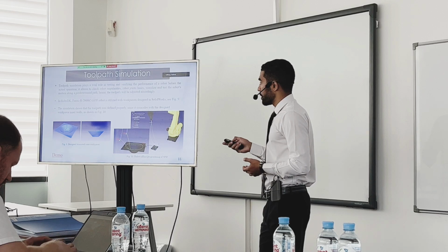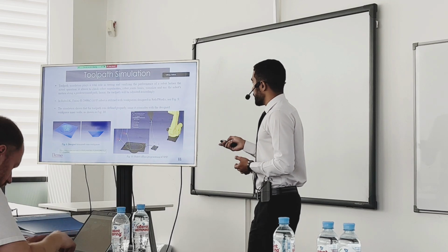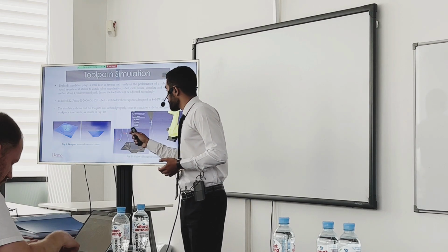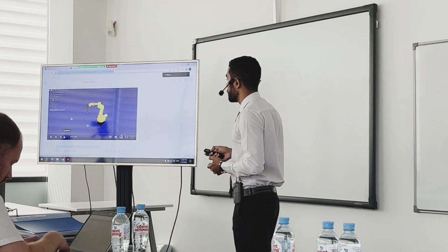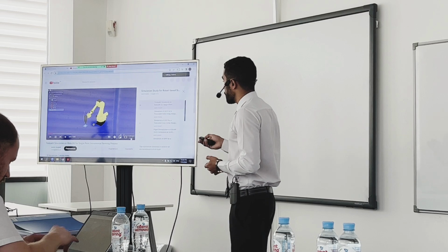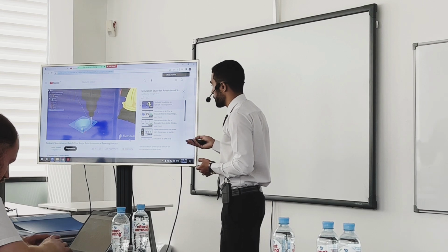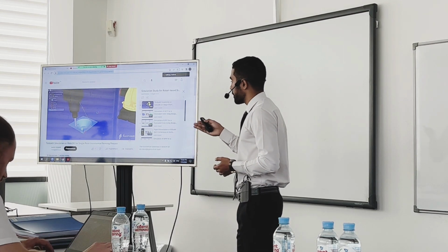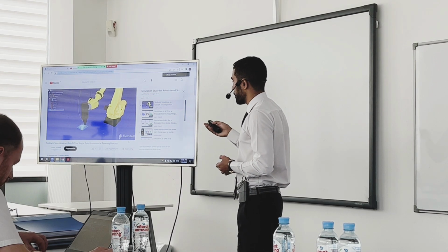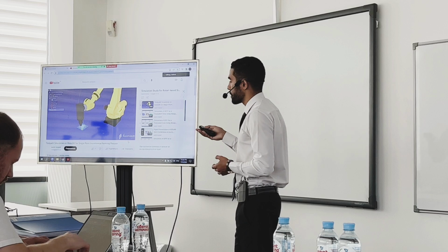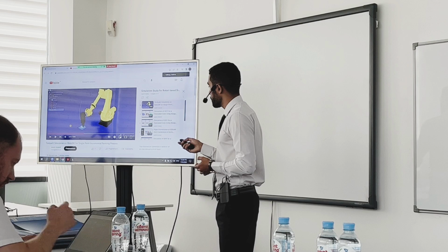So for this, I used RoboDK as an offline robot programming tool, and you can see here from the demo. Here I used a Fanuc robot, which will be similar to the ones that will be used in the experimental setup. And I used a predefined workpiece created in SolidWorks. And the simulation showed that the tool path coincides with the inner wall of the workpiece. So we can go back to the presentation.